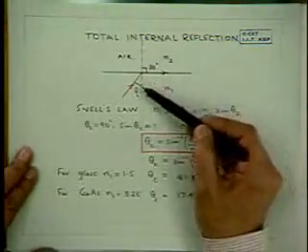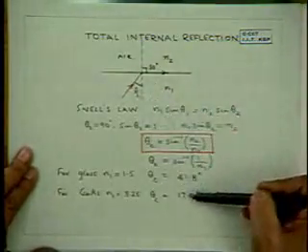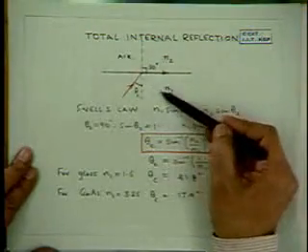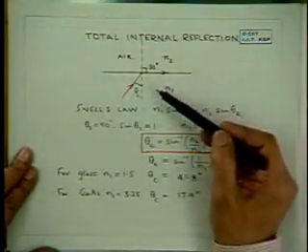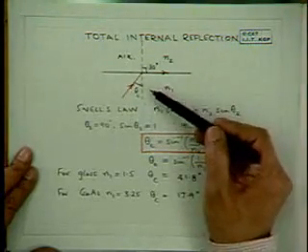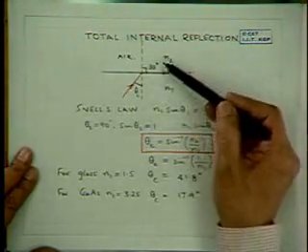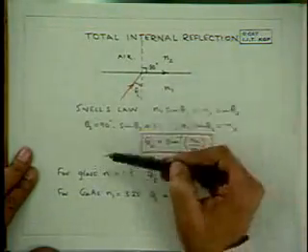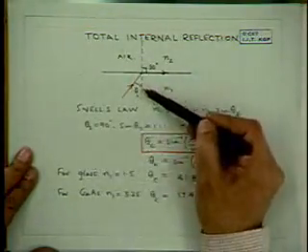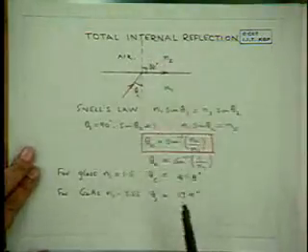Any light coming at an angle greater than, say, 17.9 will be subject to total internal reflection. This is very important in the case of light-emitting diodes, where light is generated in the semiconductor and has to be emitted into air. So there's only a small cone of radiation that can enter air from a semiconductor.